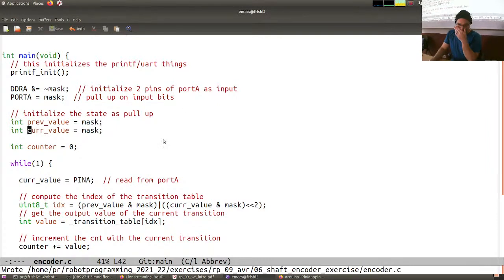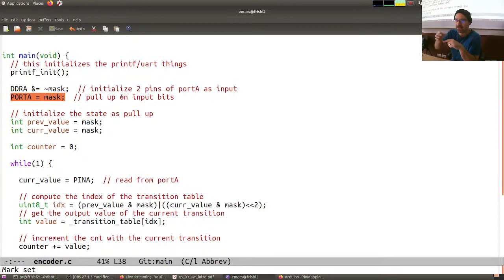All right, another operation that we would like to do is to set the pull-up resistors of the last 2 bits of the port to 1, in a way that if nothing is connected to these pins and we perform a read operation, we're going to read a 1. In this way, we can basically toggle the switch just by grounding the pin, and we do not have to have a floating wire that we move between VCC and ground, otherwise we don't know what we would read, because the pin will be floating.